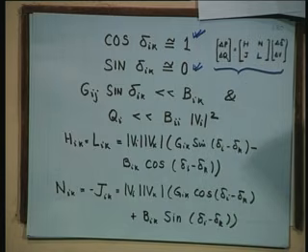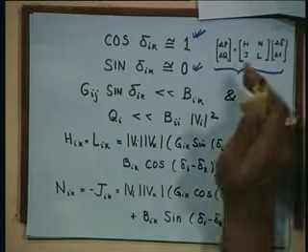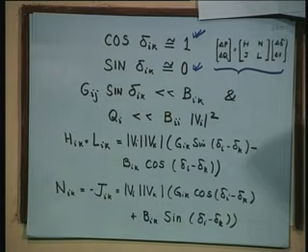But if you are fussy, you don't want to do more work, then you can replace those first order derivatives, because Jacobian was defined as the matrix whose each element is first order derivative of something: delta P by delta delta, delta P by delta V, delta Q by delta delta, delta Q by delta V. Some experts replace it by H, N, J, L. H and L are diagonal submatrices and J and N are off-diagonal submatrices.